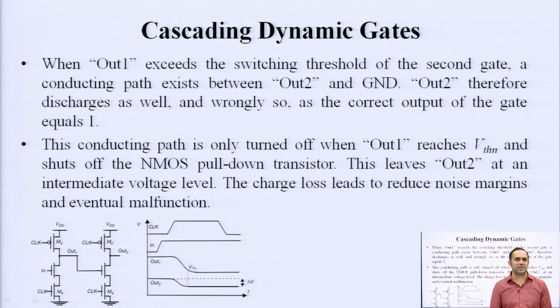So, there is a lot of time which can cover the propagation delays. So, data integrity is not affected, but in dynamic CMOS circuits, because of this continuous charging, discharging and the finite time it takes to do that, the simple cascading will definitely cause loss of charge, loss of valuable data, which again cannot be retrieved within the evaluation cycle. Okay.